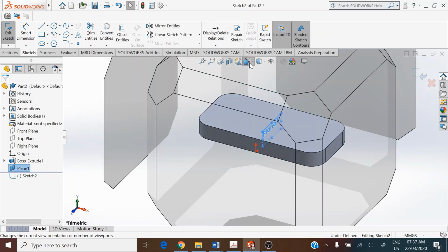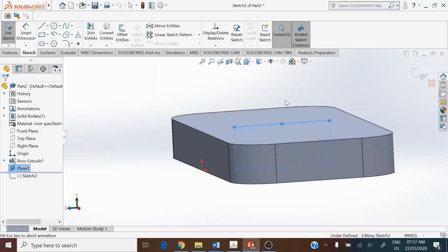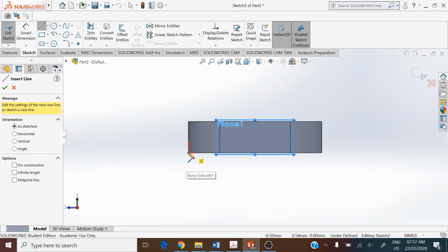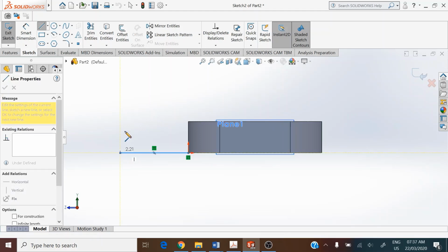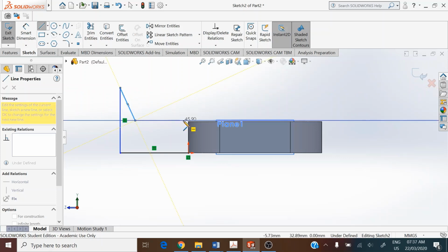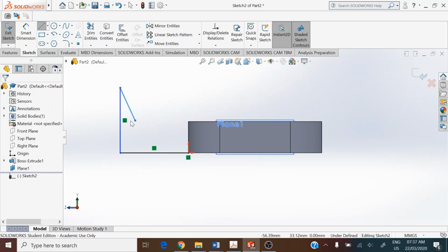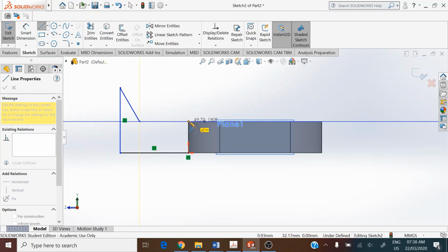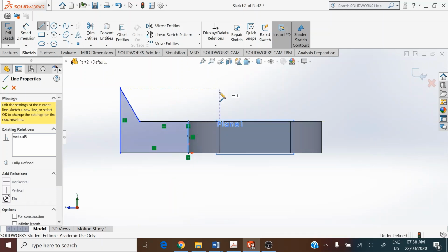Turn on the sketching, click on normal to tool in the view orientation, and then add a contour by using line as the sketching entity. You can go into the top of the base to get an inference line, and from there on you can add another horizontal line and make a closed contour.